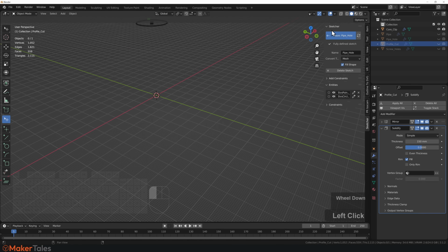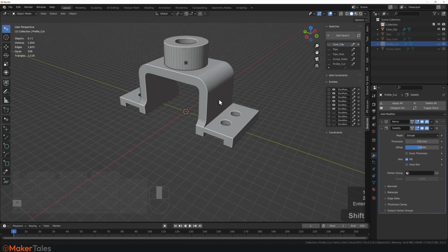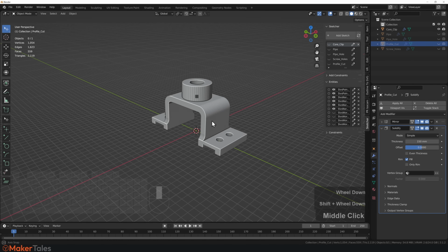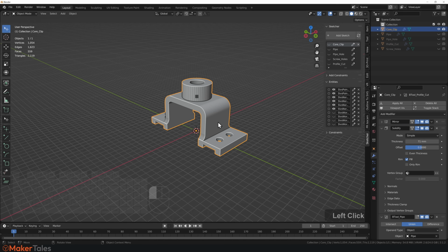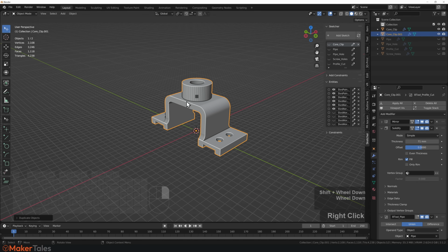I'm going to go back to those holes, oops, the screw holes that is, I'm going to change this back to what the technical drawing tells us, because we should keep to the technical drawing, right? And then with that at 12, let's leave that there, and let's get this completely ready for 3D printing, for instance. So then, to do that, all I have to do is select this, press Shift D, and you'll see that things go a little bit weird. Don't worry, just right-click, cancel the movement.